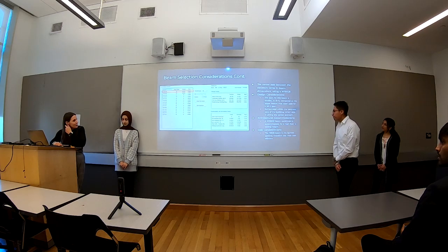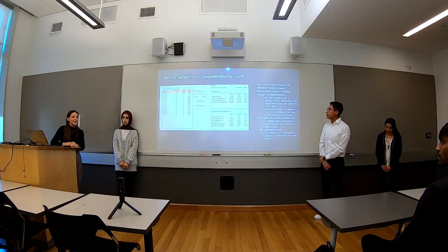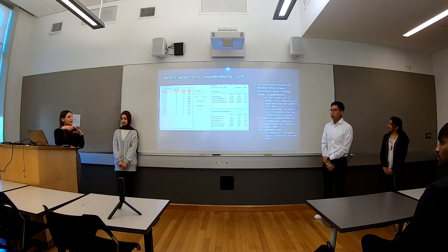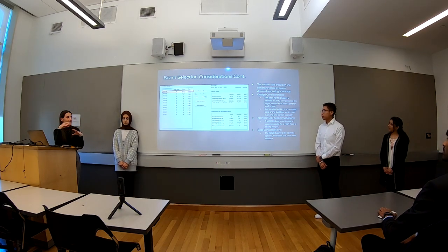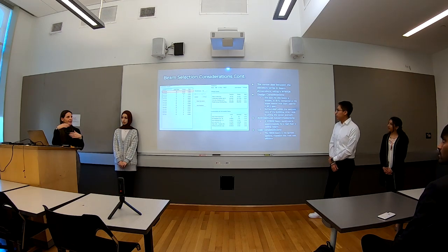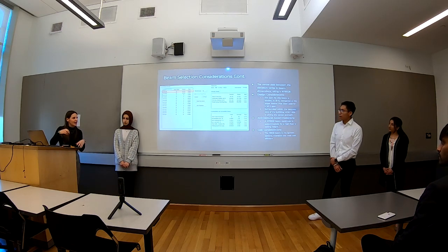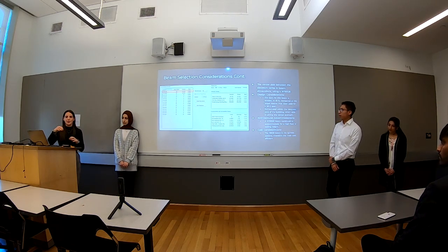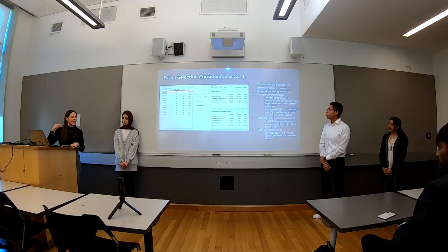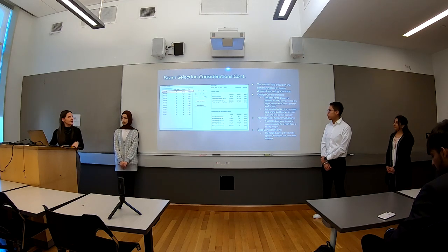So like Shivani mentioned, we also did use W16 by 26, and we used that in our center in between the elevators. So we decided to opt for the change in this section because it would allow for the smaller beam, we would have a higher floor height. So architecturally, we wanted higher ceilings. And then further than that, it was the lightest section, so most cost efficient. And then on top of that, since it was in the center, it was surrounded by our core framing. So it did have a smaller span to go across, and it did have the structural support of the core. So we decided to opt for the lightest section for this part.